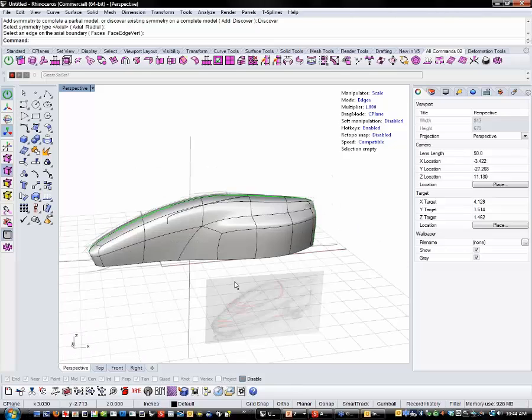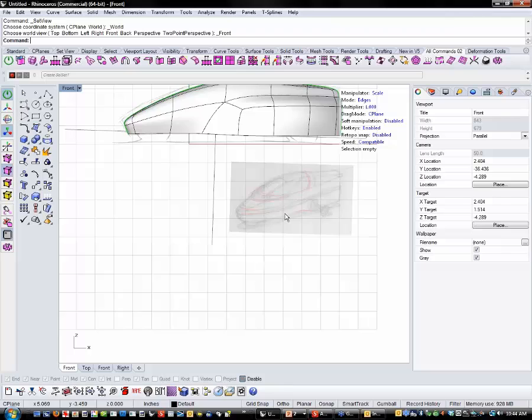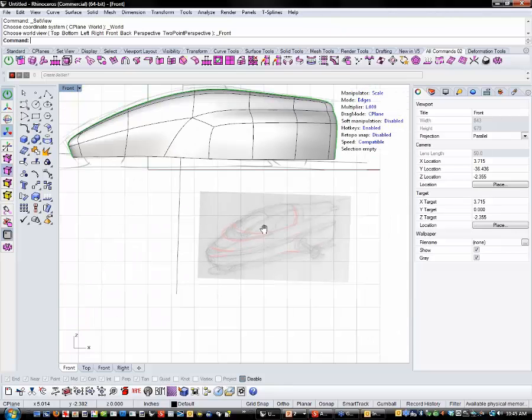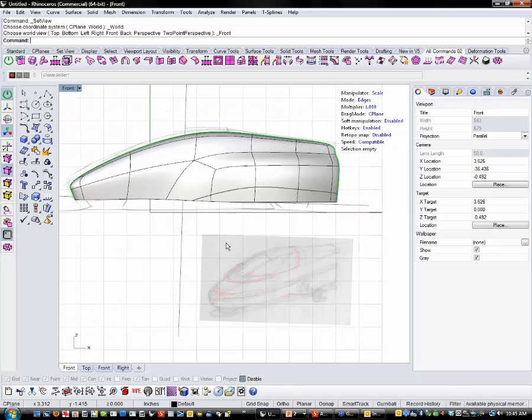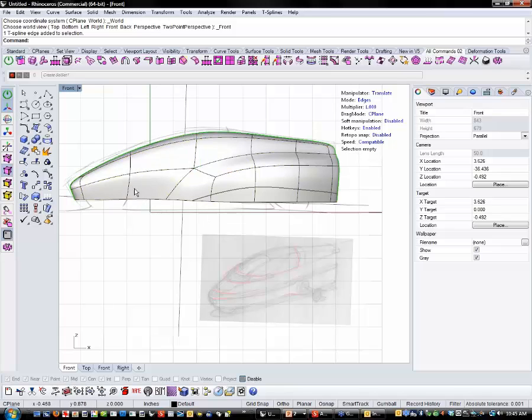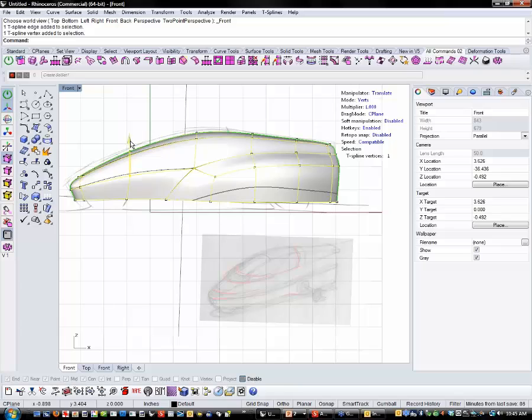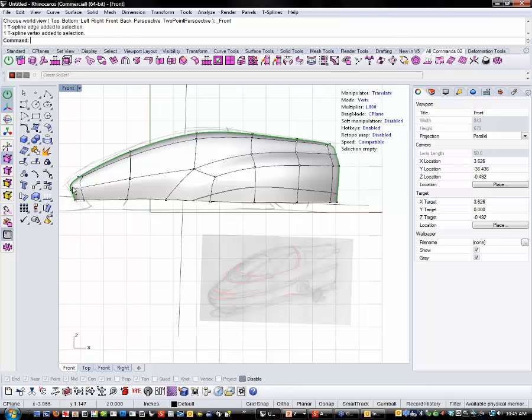So where I'm at right now, let's go back to the front view real quick and take a look at our sketch. Let's just say for sake of argument that we've got this laid out the way we want it. One of the elements that this designer was talking about was this rub strip on here. This is something that trips up a lot of people, in that they get hung up on having a model with everything in T-Splines. Well, in this case you can, but maybe not in the way you were originally thinking. Instead of trying to split this, extrude, and add this in so it's one T-spline, I know that I want this rub strip to come in here and wrap up over my rear fender. Well, I've got a nice ring of faces around there already, right?